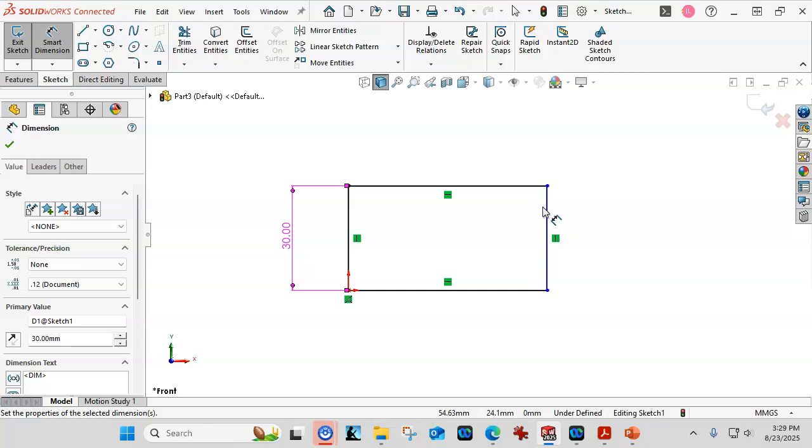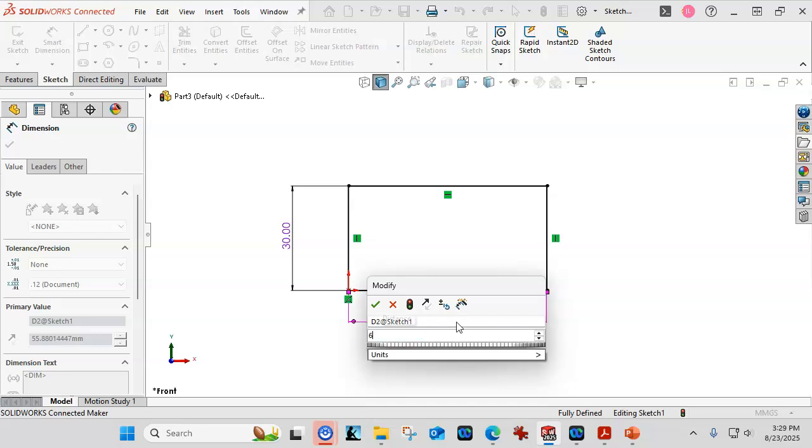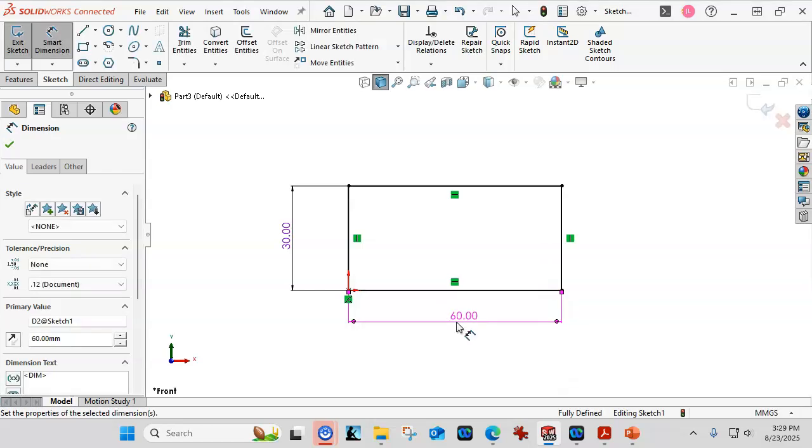And I don't have a good example of that right now other than these points can move around each other and they will stay 30 apart, but if they don't have the necessary relations, it can be kind of confusing as to what you're looking at. So let's do an example. We pick the object. I can go between two objects, and we're going to place the dimension, enter the value, and when I hit enter, now I have that value.